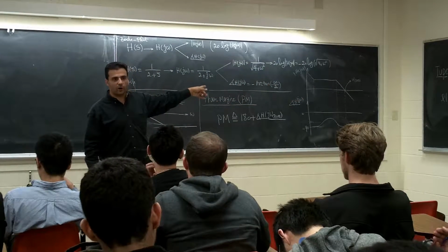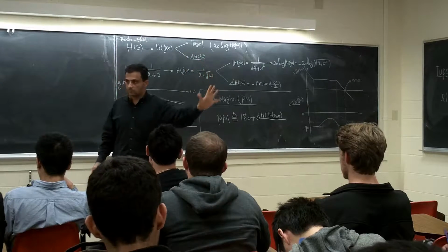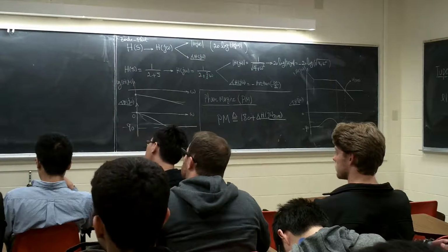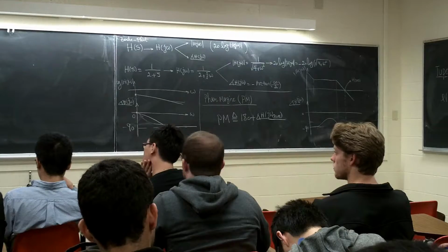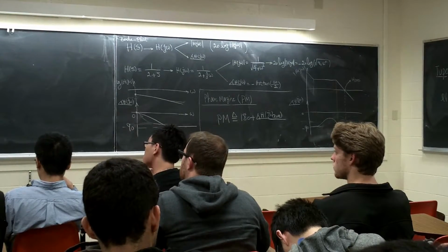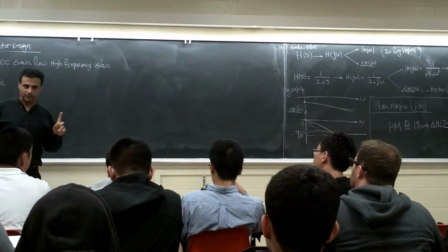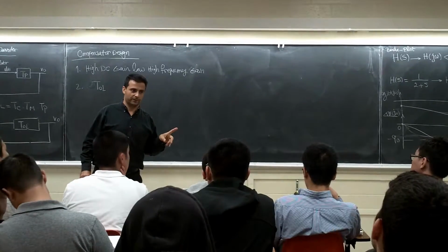We want this crossover frequency as high as possible, but much smaller than, at least 1 order of magnitude less than, the switching frequency.